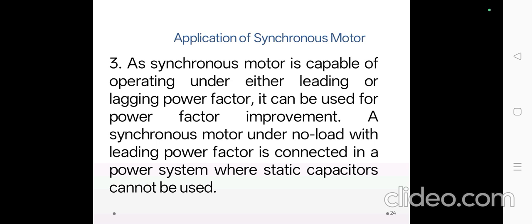For fixed active power P, the low power factor demands a large kVA rating of alternators and transformers. This increases the cost. Large current means more copper loss and poor efficiency. The large current also causes large voltage drops in the transmission line.